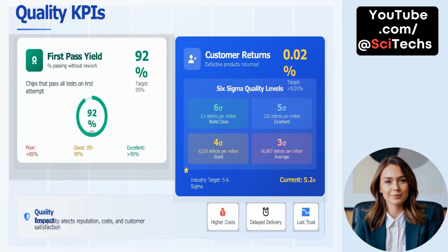Quality KPIs. First pass yield, or FPY, measures the percentage of chips that pass all tests on their first attempt without requiring rework. A high FPY indicates process stability and good quality control. Here, FPY stands at 92%, which falls into the good range of 85–95%, but below the target of 95%. Achieving excellent status requires a yield greater than 95%, which minimizes delays and production costs. Anything below 85% is considered poor, indicating frequent issues during fabrication or testing.